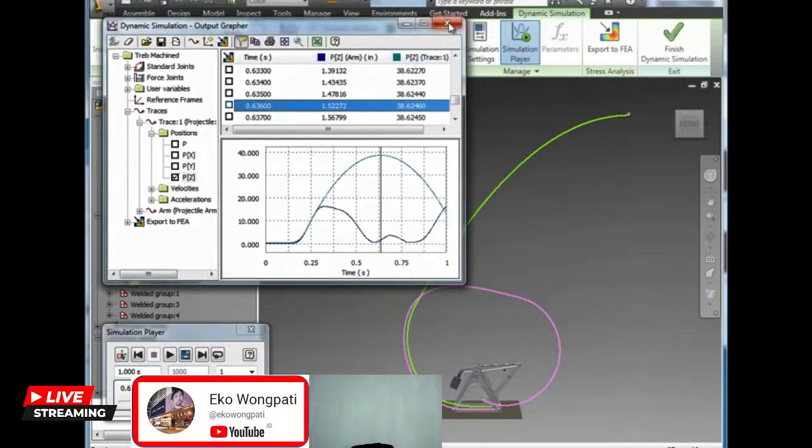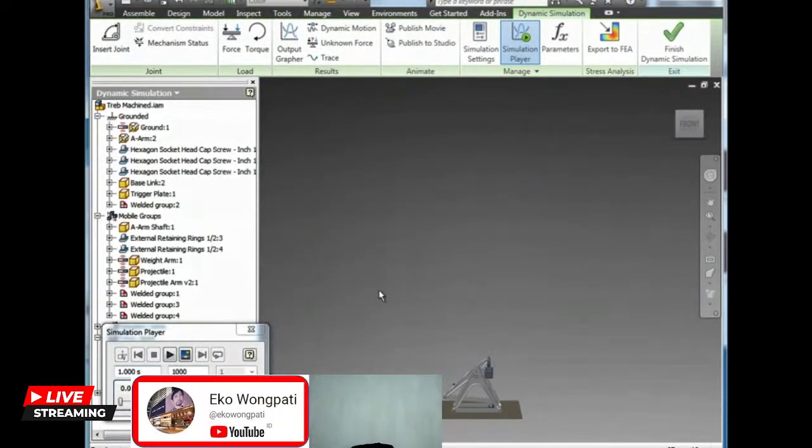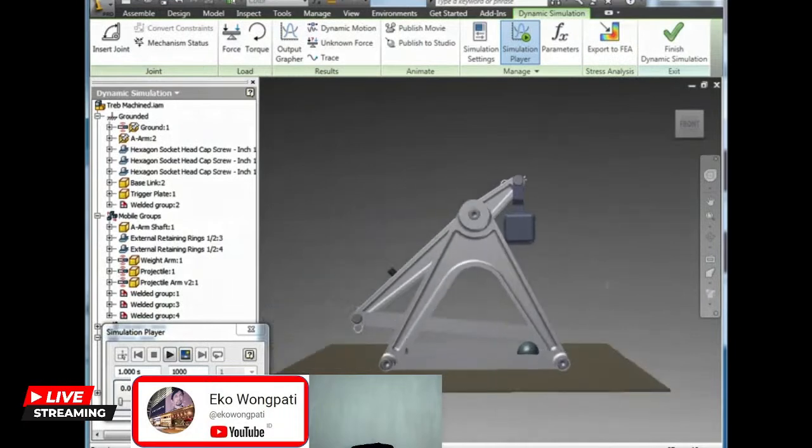So I'm going to go ahead and close out of this graph run. I'm going to go into construction mode because in order to export something into construction or into the FEA system, you actually have to tell the simulation environment that you want to export it before you run a simulation so that it can collect the data needed to do the export.